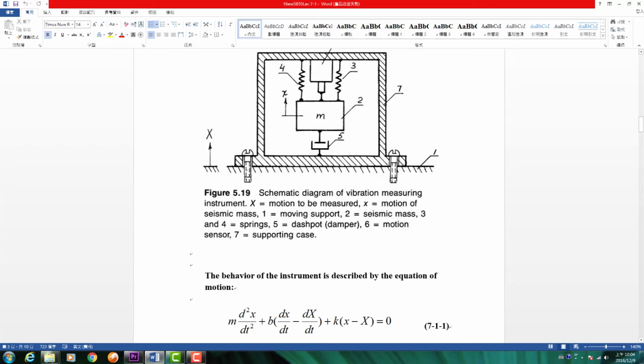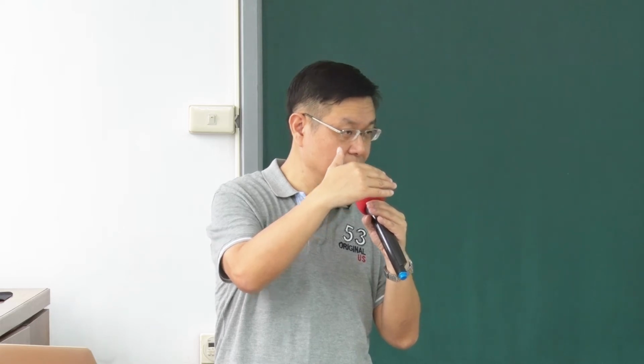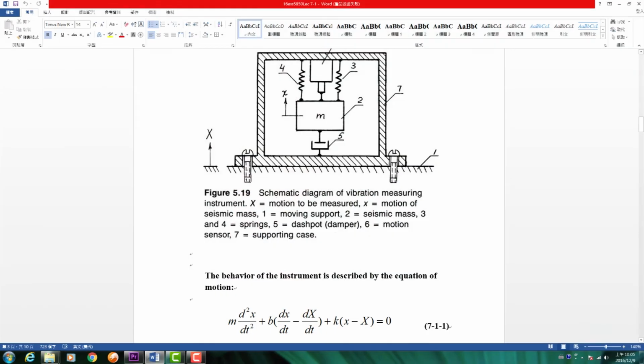And then we think of the differences of the small mass and the large mass, there's a displacement between them, okay? The distance change. So the distance change is not a static situation. It's a dynamic situation. That means there's an acceleration between them. So that means not only a distance change, but there's also a corresponding speed between them. Okay, the moving speed. So the moving speed will be the first derivative of the distance. So the relative distance variation, or the relative speed, will be dx_small/dt minus dx_large/dt.